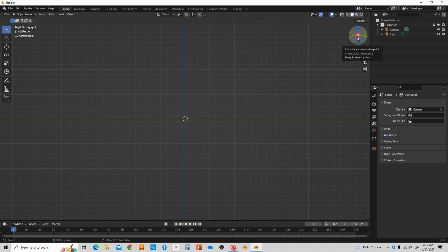So we're going to go to X. Oh, here's the cool part too. If you click the same axis twice, then it'll flip it, do a 180 flip, so it'll go to the other side of the vehicle. So we're going to say an X, so the front of the vehicle can face minus Y.